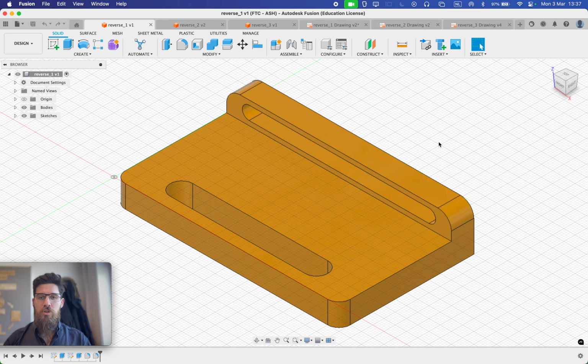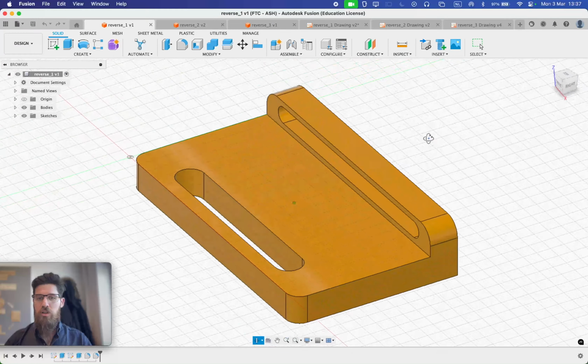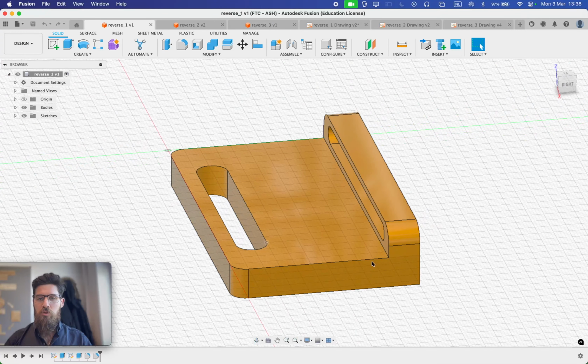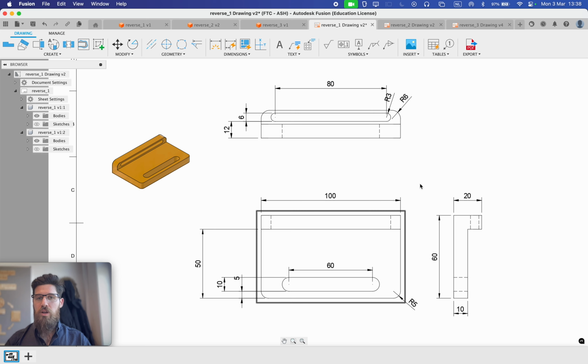Let's take a look at the first object here. This is a simple angled bracket with a large slot in the side. You might mount this onto a piece, mount another piece over here, and having a slot so that it can be angled and moved to the side. The drawing with all these specific dimensions for it is right here. If you remember the little R that denotes a radius, specifically pointing to a section around these.